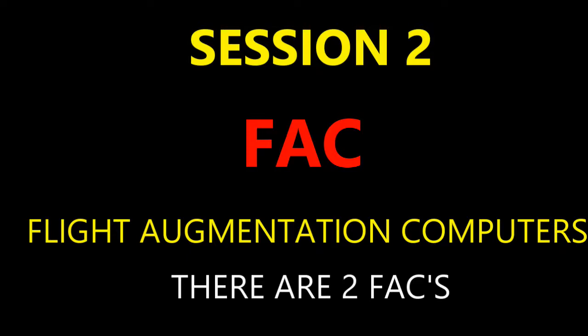However, let's just say you have one problem with one of the rudder trims. Then the amber indication is going to show up on the display, but the master caution light is not going to come on in that case. It won't come on, and you don't have to reset anything when there's only a single fault. As far as FAC 1 or 2, if one of them's out, then you don't need to do anything. There's no reset that's necessary. And that goes for that as well as the travel limitation.